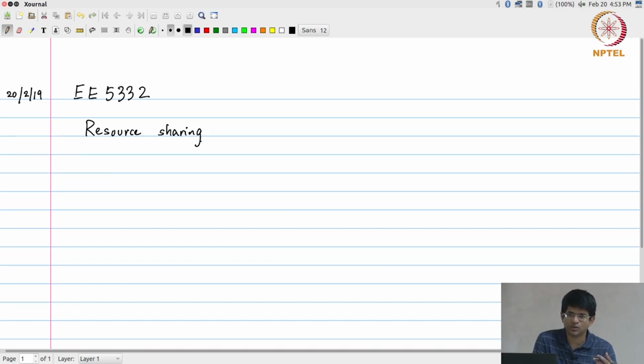And we used two approaches. One was to parallelize the computation, use more hardware. Alternatively we said, I don't want to add more functional units, I will add only registers, and by means of pipelining or retiming, basically moving registers around inside the data flow graph, I can reduce my critical path.